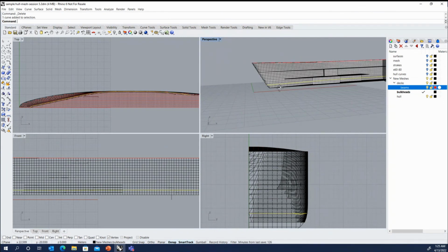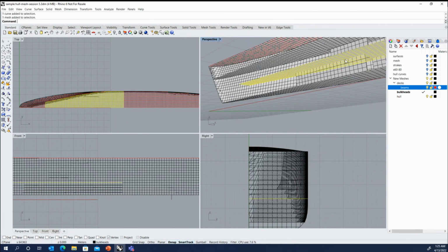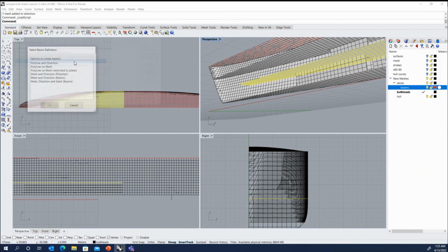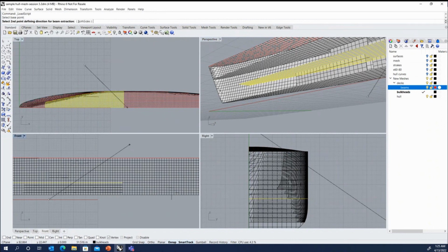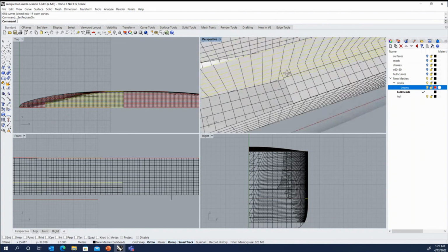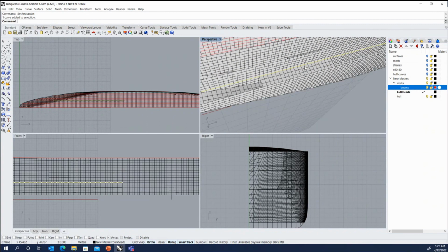Now, when you go to extract curves on the deck, you may have a bulkhead underneath where you want to delete part of a stiffener, but you want to keep a portion before it and a portion after it. So if we extract these curves, just create the polylines again, and I'll set ortho on. Fairly tight tolerance. We have our curves there. And you can see this curve is going to interfere with our bulkhead.